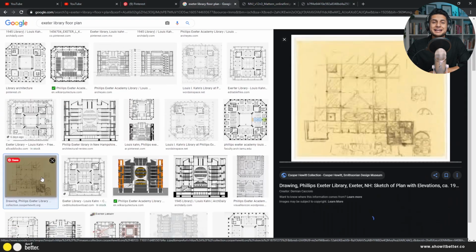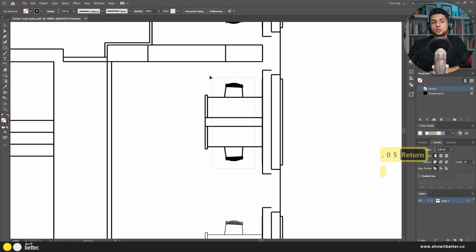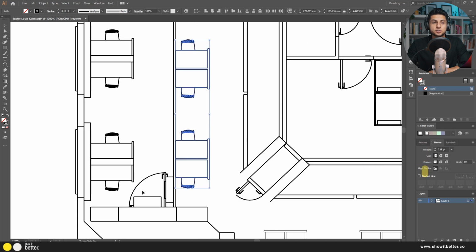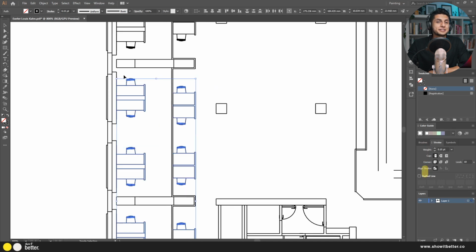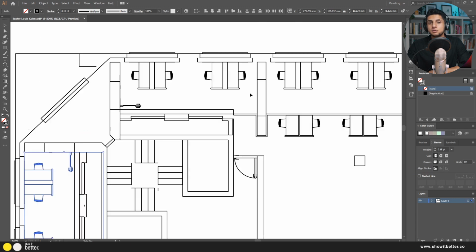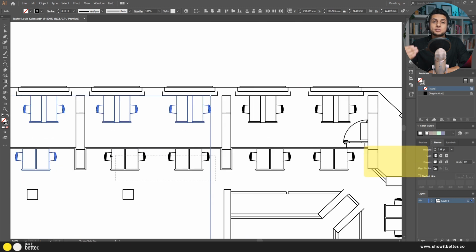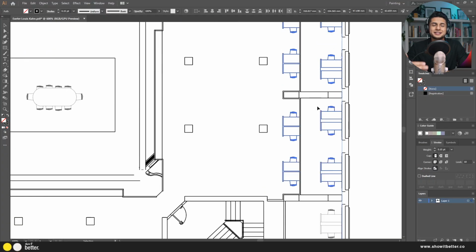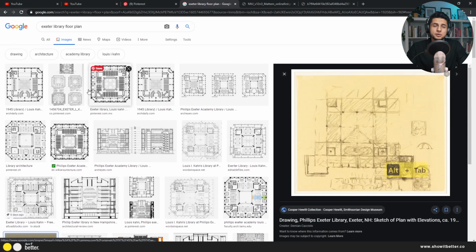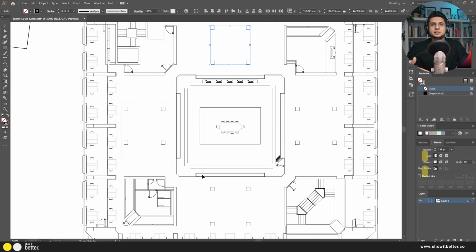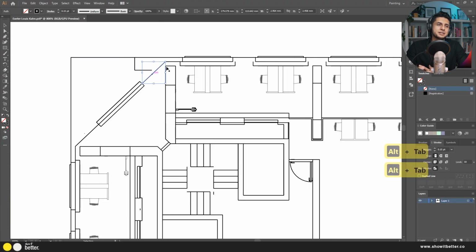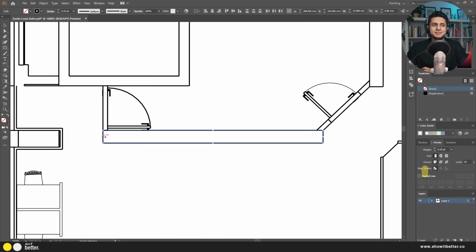As soon as I had that, I started changing the intensities of the furniture versus the actual architecture. So for the furniture, I selected all the furniture, which was chairs, tables, etc. And then I reduced the line weight much more to a 0.05, I think. And I also selected all the lines and changed the color so it wasn't a true black. It was more like an off black, which I think is much more interesting, and it's a subtle change that can make the image look a little bit better. So this honestly took a while, and after that I wanted to start to add patterns.